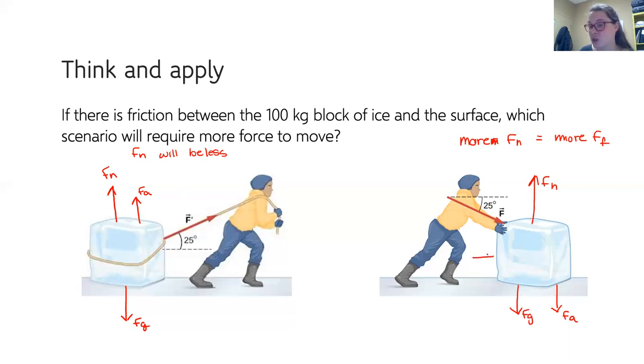I would recommend you push either perfectly face onto it so you don't have that vector, so that normal force is equal to gravity, or in a best case scenario, find a way to tie around and pull it. Pulling is typically easier than pushing just because you have less friction force. It may not be a lot, but any reduction in work is better than no reduction in work. So hopefully that gives you a good understanding of how forces work, gives you some good background, and lets you go through and work at your quiz.